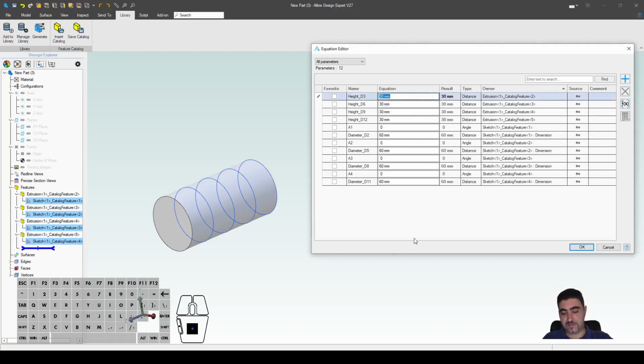Okay, so let's say that this has a height of 100 and a diameter, here are the diameters, and it's got a diameter of 20, right? And then I want a bearing seat, and my bearing seat is 20 millimeters and 13 millimeters as the bore of the bearing. I didn't look up standard bearing values before I did this.